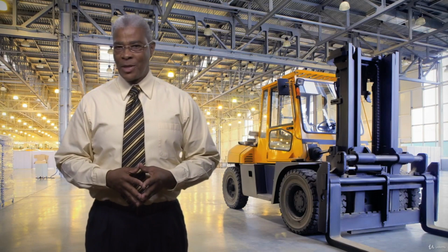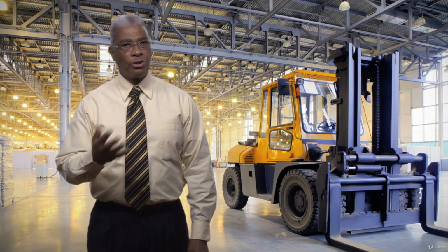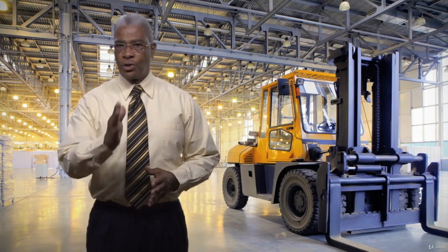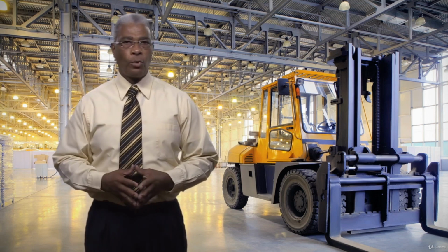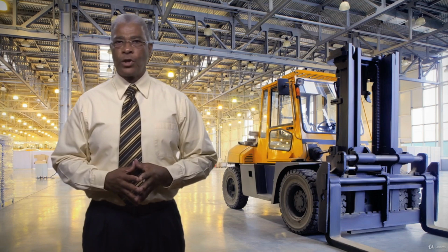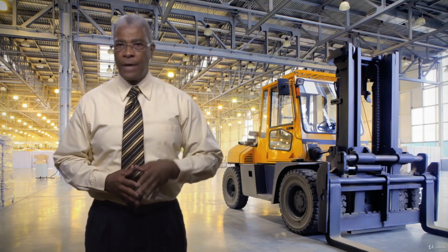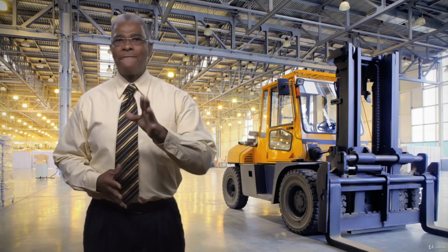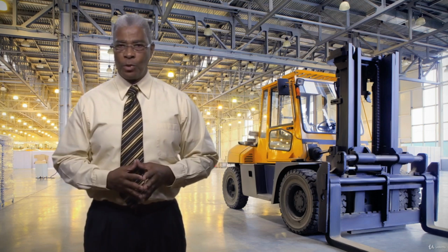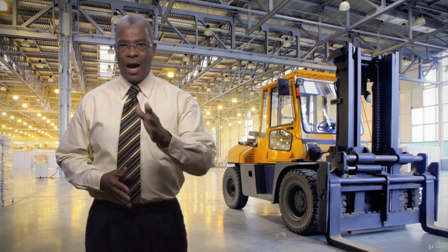Authorized employees must possess the knowledge and skills necessary for the safe application, use, and removal for controlling energy of all types. Affected employees, usually the machine operators or users, and all other employees whose work operations may be in the area of the energy controls, need to recognize when the control procedure is being set in motion, but they do not perform the actual lockout or tagout of the systems being worked on or tested. Affected workers need to understand the purpose of the procedure and the importance of not using or starting up any equipment or machines that are locked out or tagged out.